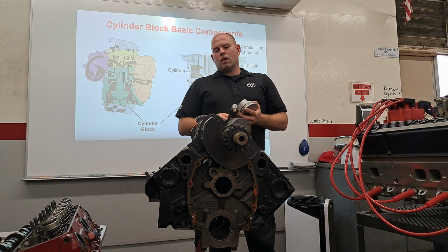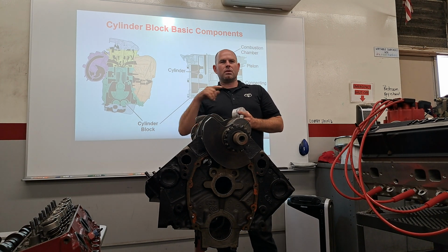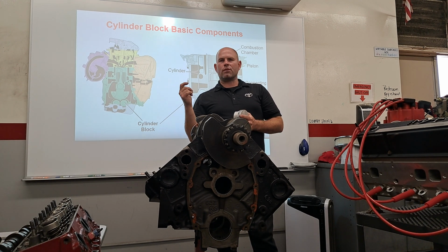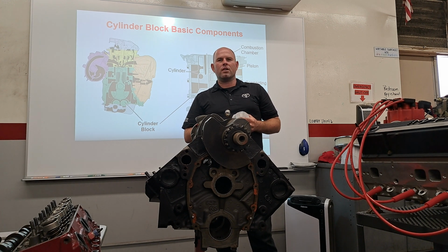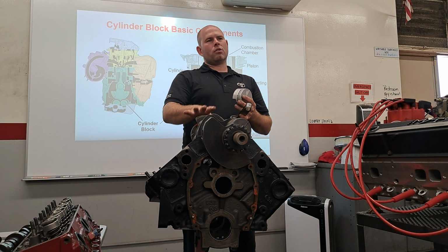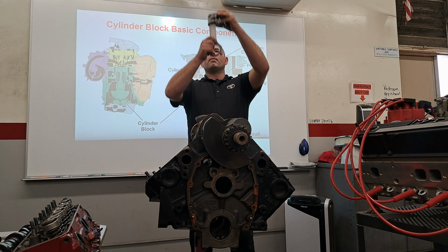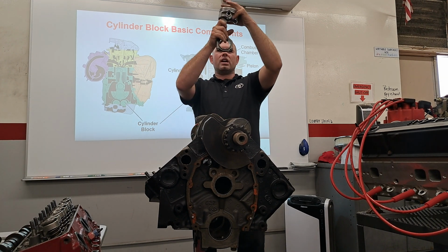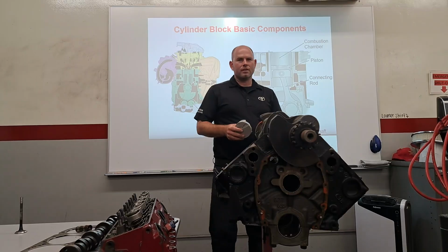Additionally, that flex plate or flywheel is what we attach to the transmission, and that's what makes the transmission turn. And ultimately, the transmission turning turns a differential, drive shaft, depending on exactly how it's laid out, even if it's a front wheel drive. All the power starts and ends really at the crankshaft. So the crankshaft's a big important piece. That makes sense? So if we're pumping, intake comes down, compression goes up, power. Pause for 1 second. All right, so you guys kind of can see the motion, right?